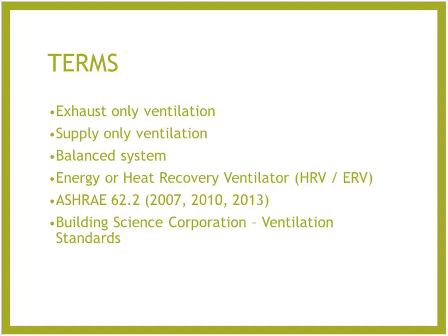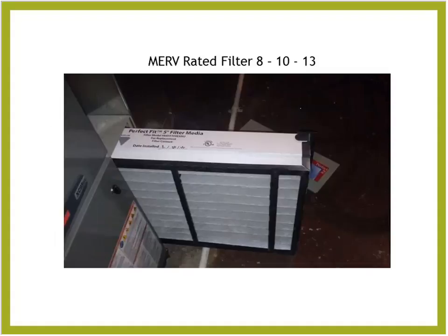And then the Building Science Corporation has come out with their own ventilation standards because they believe that ASHRAE may actually over-ventilate units. So if you want to check that out, you can go to Building Science Corporation's website and check out their ventilation standards as well, if you're concerned about over-ventilation with your clients. So another real simple thing, MERV-rated filters. If you're switching out your client's heating and cooling system, make sure to get higher MERV-rated filters.